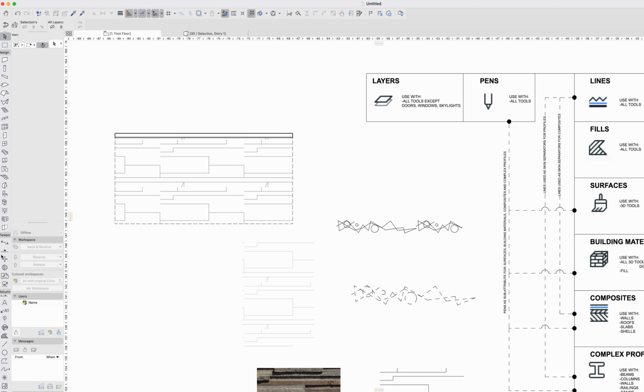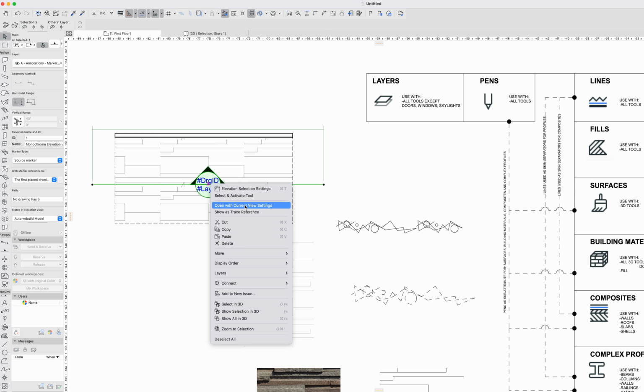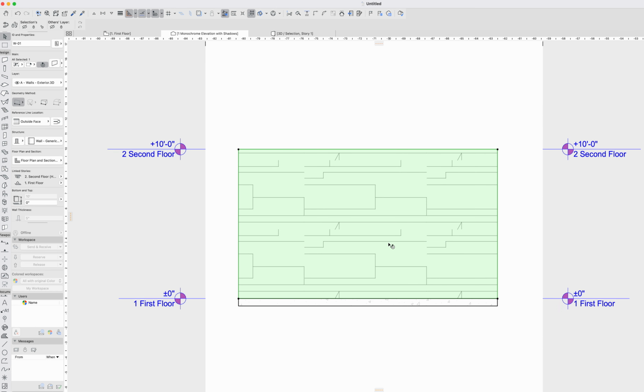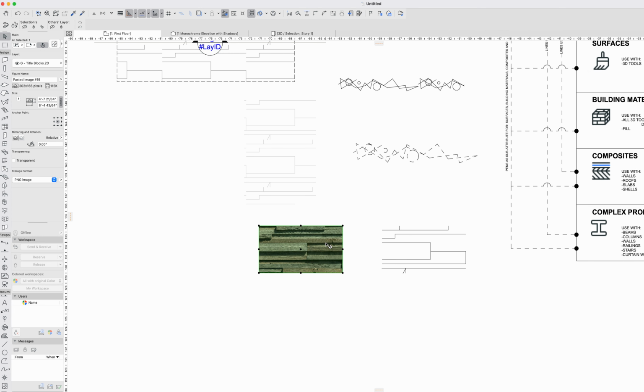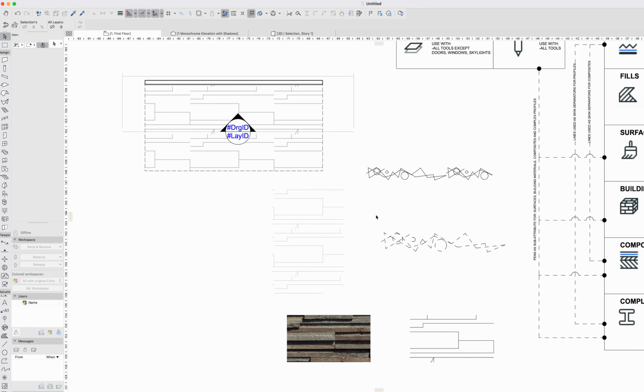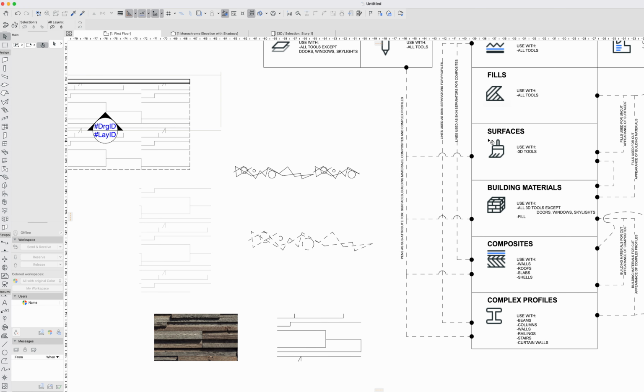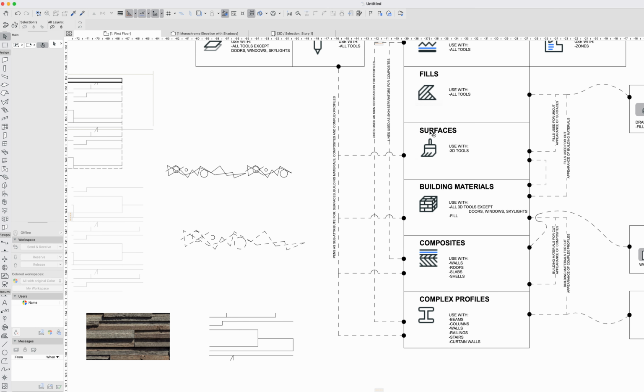Now if we dump in an elevation of that wall, we're going to see that wall with that same stone pattern applied to it. Obviously, we would want to be careful that our JPEG was scaled properly, that we traced it out, that it was all repeating, that we didn't get these sort of weird, irregular repeating patterns of it. But conceptually, that's how that works. The surface fills get applied to the surfaces, which get applied to the elements, the modeling elements.